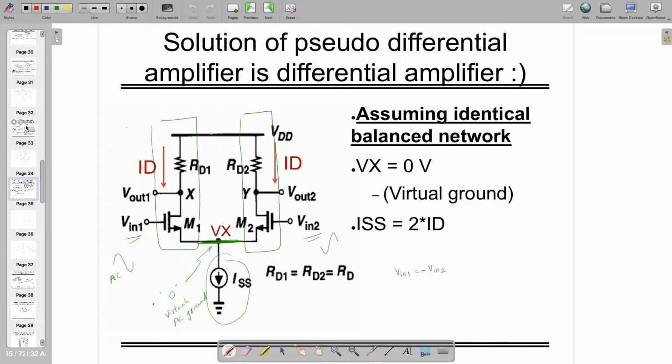And that's what is happening in our circuit. Here the output common mode voltage is actually decided by two parts. One is the current and one is also the input common mode voltage, but its impact is very low. The current flowing through these two branches depends only on this one, and it depends on the fact of what input common mode voltage you are giving there. Sometimes even if it's going into cutoff, this whole phenomenon will still work.